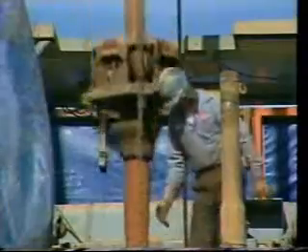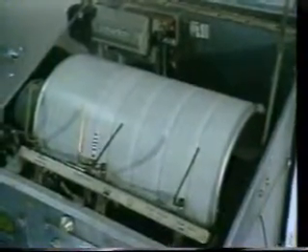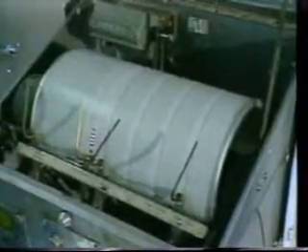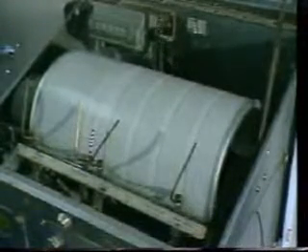With the new joint now a part of the string, the pipe is picked up, the slips removed, and the drill string lowered back to bottom, now one joint longer. When the Kelly bushing fits into the rotary table, the process of drilling down the Kelly starts once more. Each time a connection is made, there's an indication here on the depth and drill rate recorder, which is usually located in the doghouse near the drill floor.